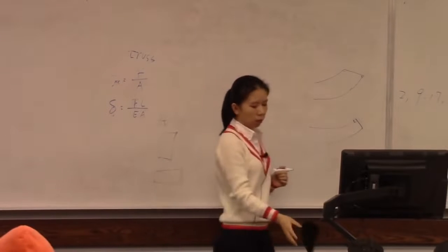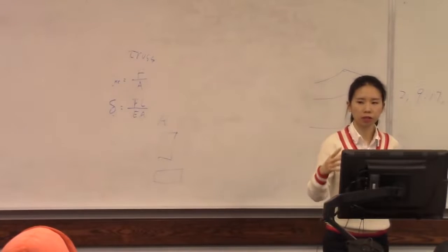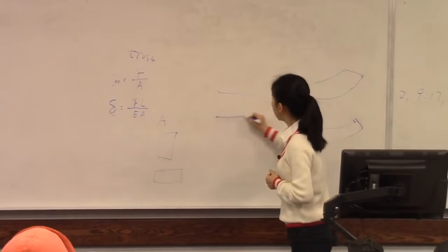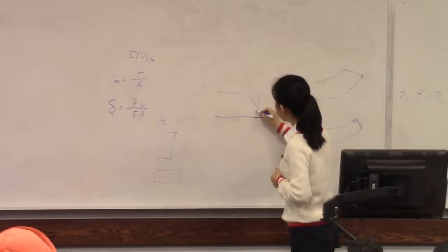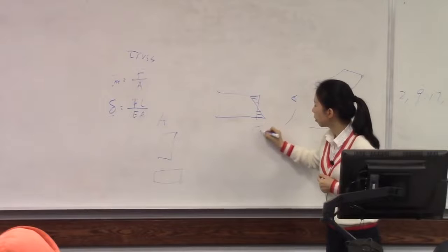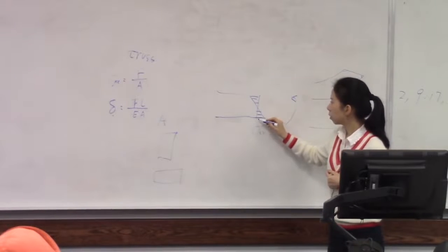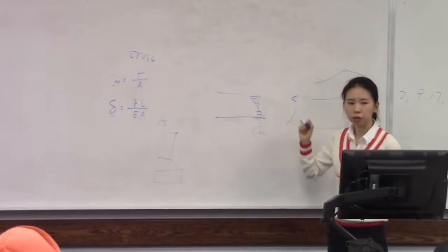So for a truss problem, the sigma axis, no matter whether it's the bottom surface or upper surface, is always the same, right? But for a beam problem, if you bend it, for example, if I want to bend it this way, and then like this, right? The sigma xx changes linearly through the cross-section direction. So the sigma xx on the bottom surface and upper surface is different.